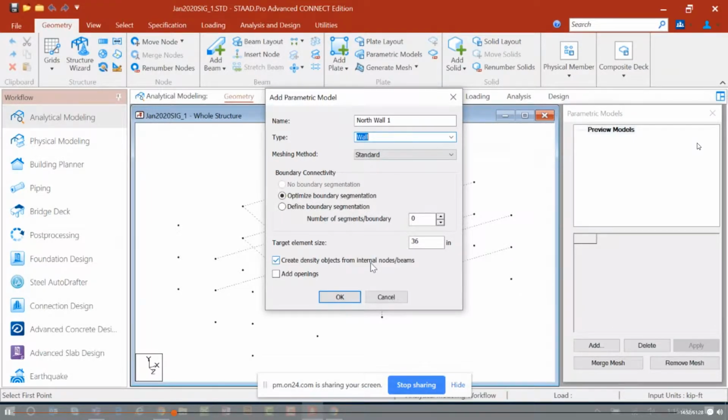So we talked a little bit about, we do recommend a different wall, a different parametric model for each level of the structure. We should also mention that currently openings within parametric models are not being brought over to the RCDC, and it is looking for walls that are pretty regular of shape. So you want like a constant height and a constant thickness. So just keep that in mind to make sure that this workflow works for you.